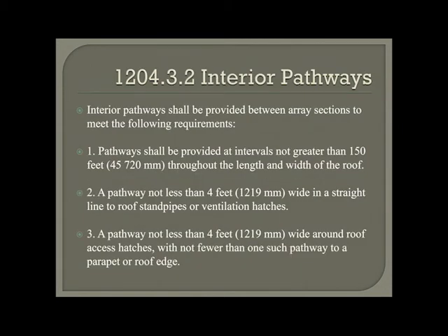Okay. And depending on how much they're putting up there, then we need interior pathways. So essentially we need a break in the panels every 150 feet. So if you have a large structure that's spanning 300 feet, you're going to have a section of panels, 4-foot break, another section of panels. For the most part is what we're looking at.